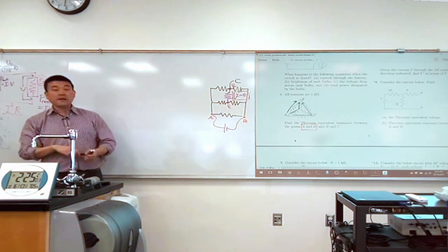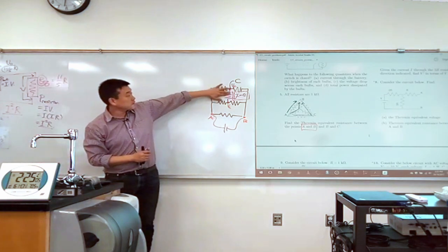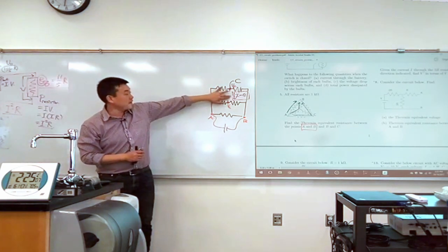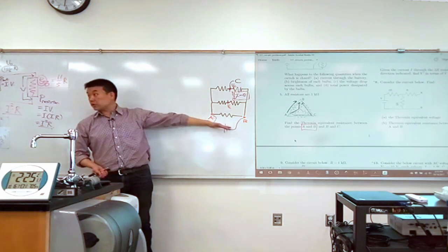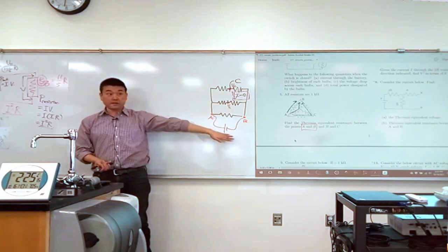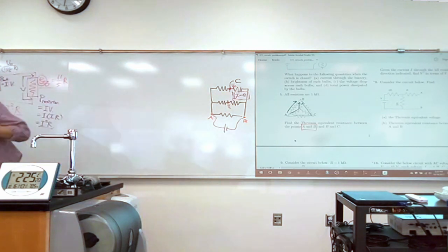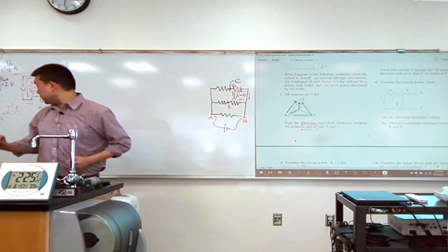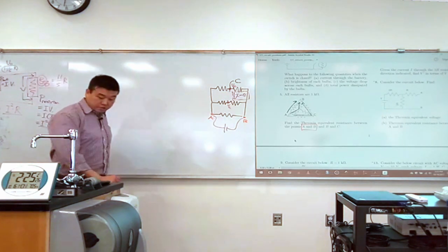And once you get that far, then the thing that you can do with the circuit simplification is you can say, oh, this resistor might as well not be there. And once you don't have that resistor, then you can do the rest of the question. Add in series, add the whole thing in parallel. Good. So this idea of simplifying circuits is useful in doing simple questions.